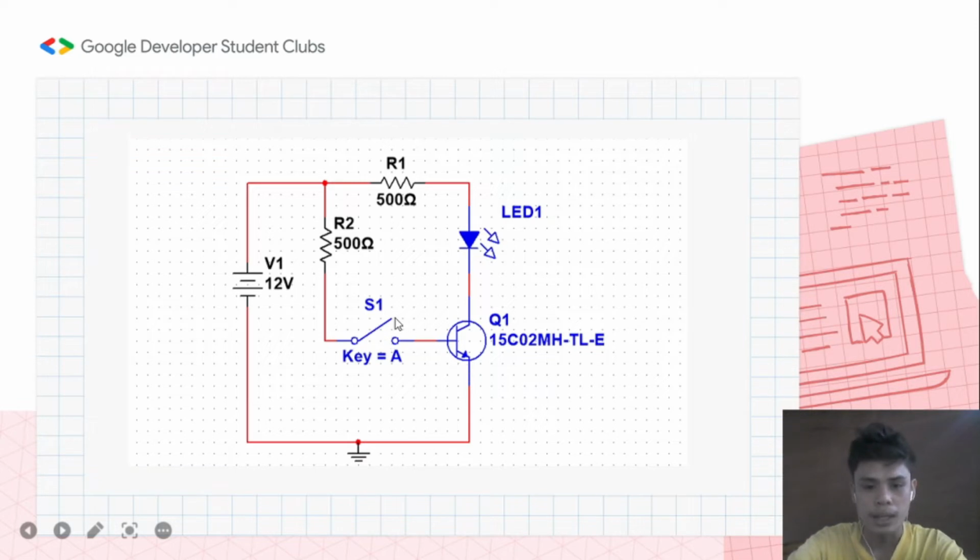So as our transistor is turned off, we can assume that this circuit is an open circuit, since it is off, so there is no current flowing. However, if we apply current to the base, then we're actually allowing current to flow through this portion from the collector to the emitter. Then our circuit is completed, and as a result our LED, we can assume, is on.